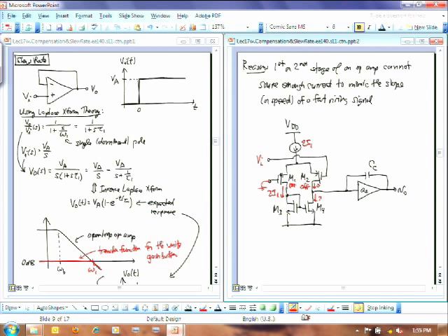And you control how much of that 2I1 gets to the output by controlling which one of these devices is on or off. And if you go all the way and shut this device off, keep this guy completely on, that then puts all the 2I1 through here. It takes all the 2I1 out there. That's all the current we've got to take out of this capacitor right here. And of course, the charge across that capacitor determines what that output voltage is.